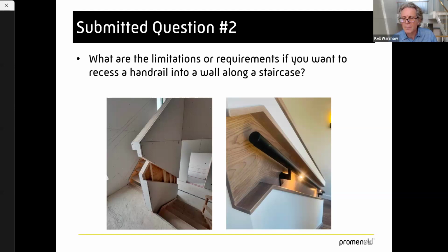So you have the ability to play with the spacing and the intensity of the lights to create various lighting effects. It's much more versatile than strip lighting, but also much more durable because these are high intensity, high lifetime lighting. It works indoors and outdoors, as you saw in the Orlando project earlier. 60,000 hours rating, typically much longer, especially if you dim them. It's kind of a lifetime light that you can put in there. Speaking of life, they also meet the life safety requirements.